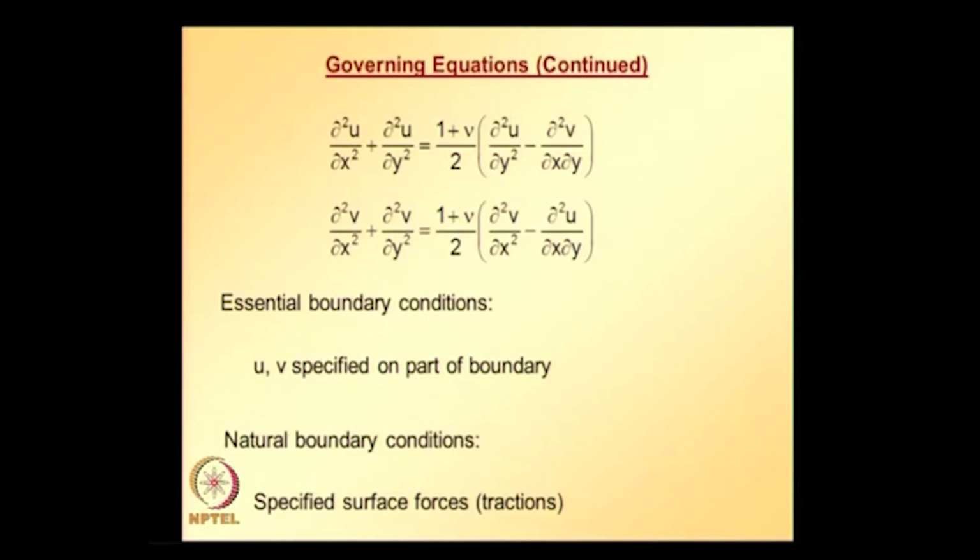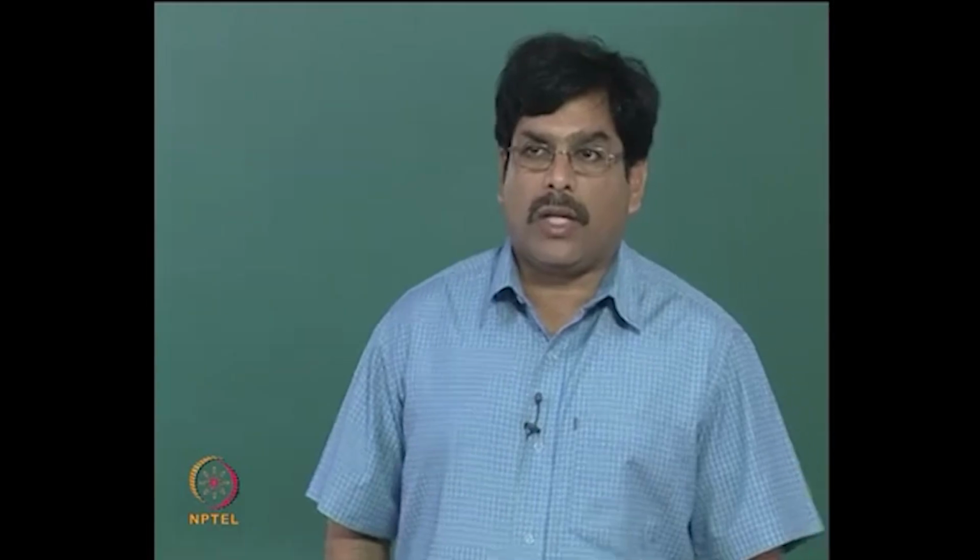When I made the statement that the specified surface forces are first order, that is based on what we did in the last class, that is, expressing tractions in terms of stresses and stresses in terms of displacements via stress strain and strain displacement relations. Finally, we can see tractions are related to the first derivative of displacements, which are natural boundary conditions.